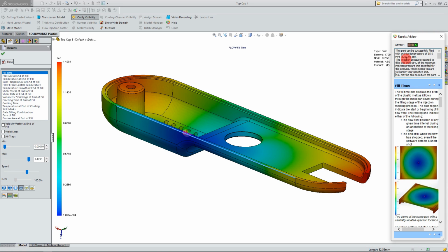Generally speaking, you want to make sure that the amount of psi of material coming into the mold is a certain factor of safety less than the machine's capability. The reason for this is you don't want to push the machine's limits. If you see a yellow light come up here, then you're within a range that's kind of in the middle. And if the red light comes up, it likely means that you're pushing the limits of the machine. The amount of psi you have is approaching or above the maximum psi limit that the machine has based on our inputs.